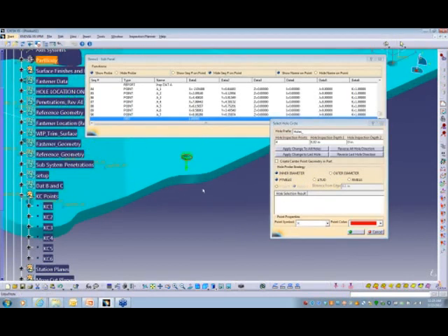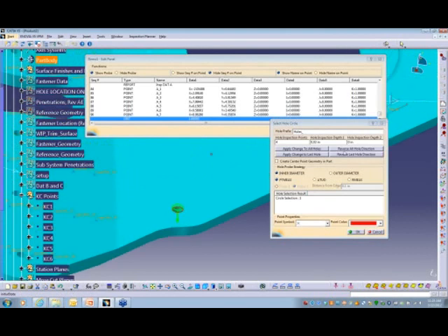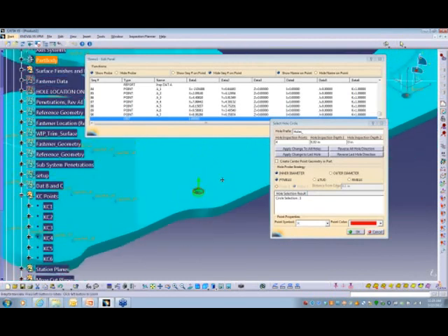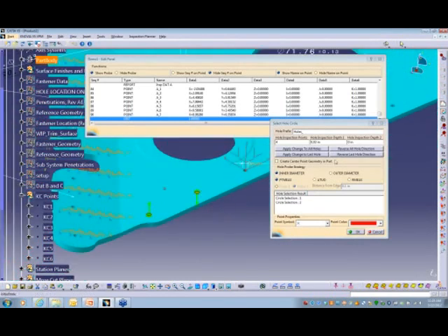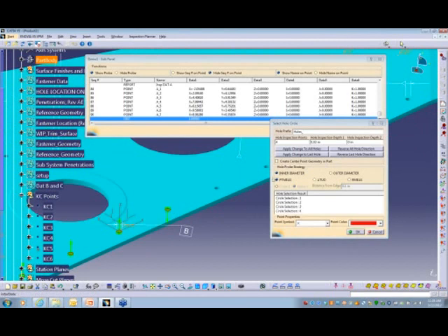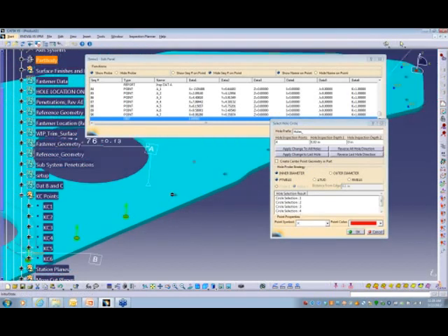All you basically do is pick the curve, reverse this. That shows you the strategy. We're down 30 thousandths. We're going to approach it from the top as fast as you can pick the hole. And you can reverse these all at once if you want. I could have picked them all and then reversed them, which I probably should have done.